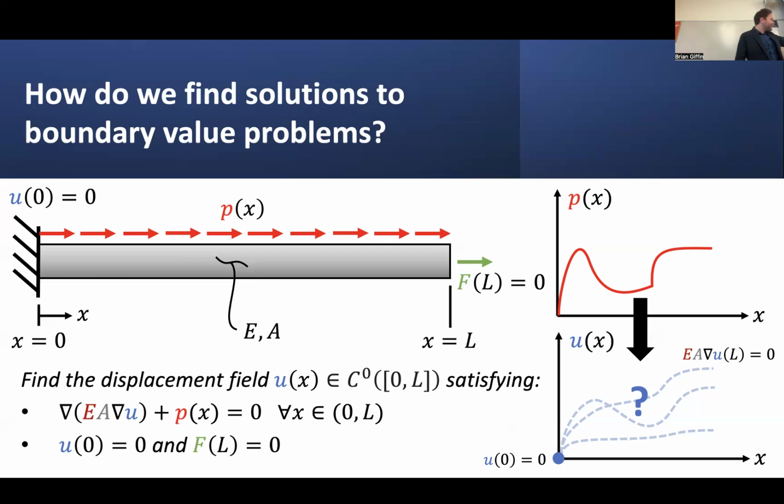sense. And it also has to satisfy these boundary conditions, either constraints directly on the displacement at prescribed support locations or constraints imposed on what's the externally applied force at maybe this end of the membrane. So that's what a boundary value problem is. It's a statement of, we're going to solve this structural analysis problem for this unknown displacement function or this displacement field. All right, well, that's very nice.